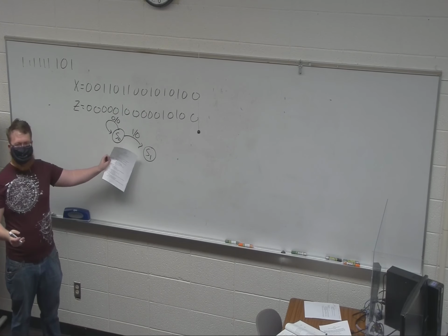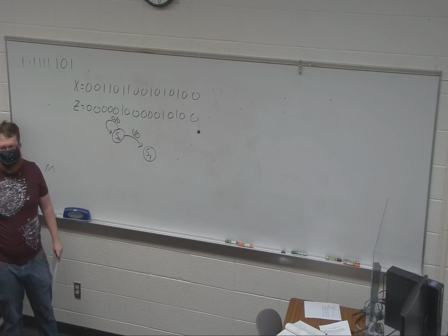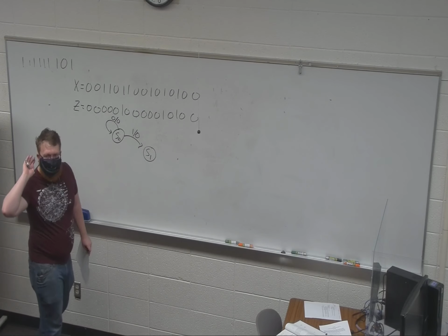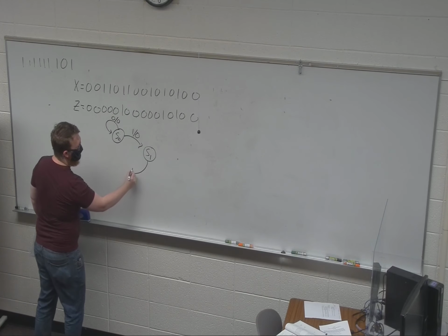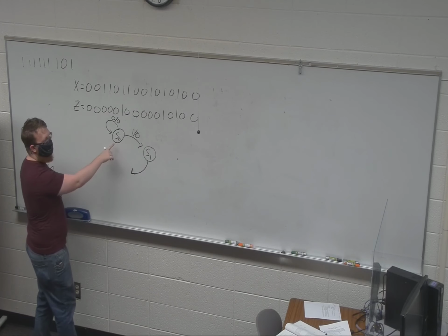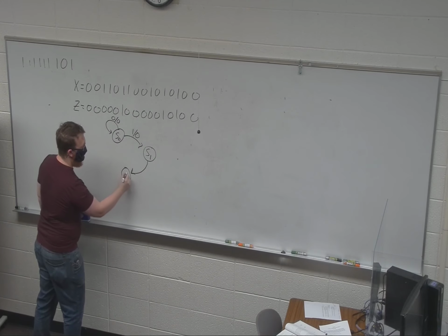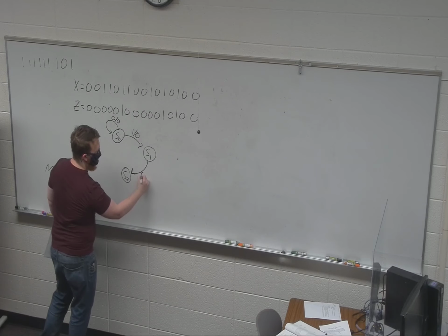So now we're sitting here, we've seen a 1. What are the two things that can happen? Okay, so if I see a 0, what happens? You see a 0? Keeps going. You're going to go to a new state, because this state has no way of making an output high. So it saw a 0, and the output is still 0.